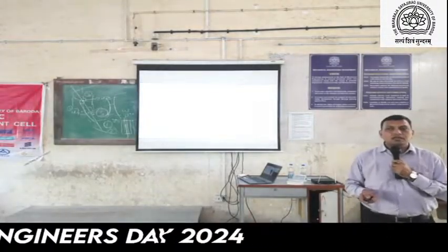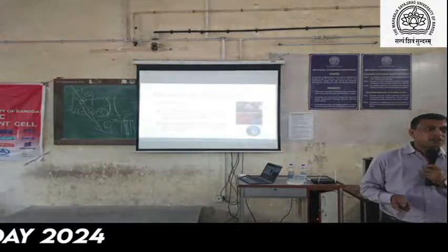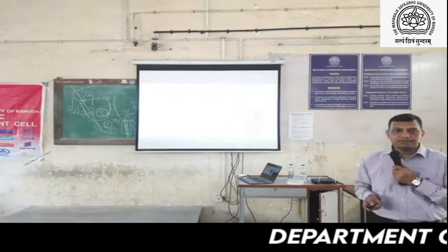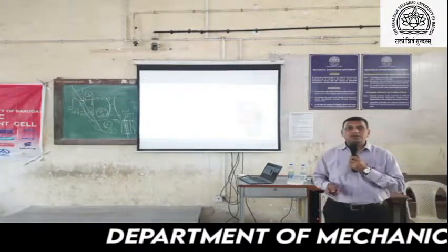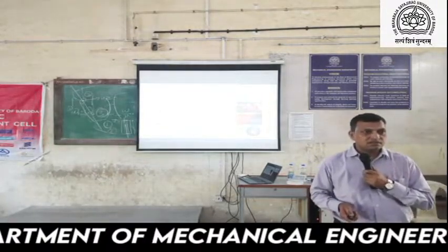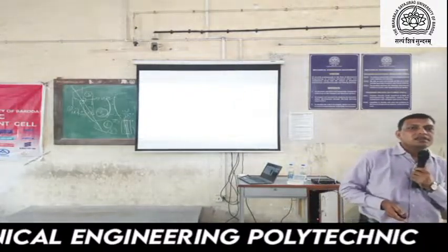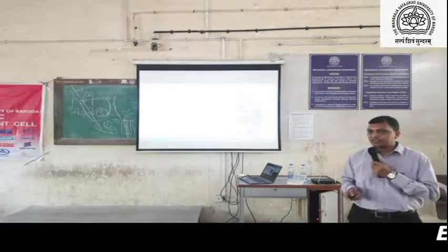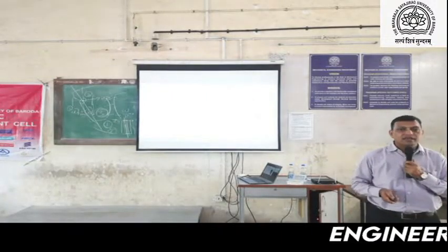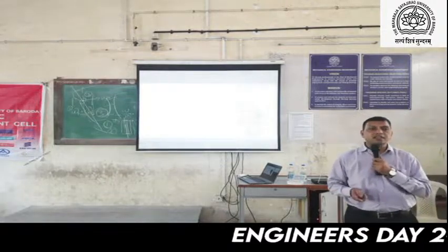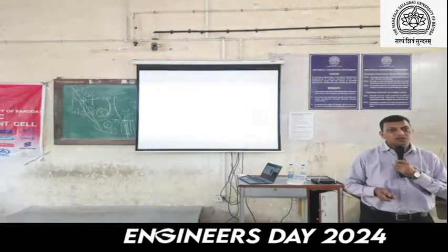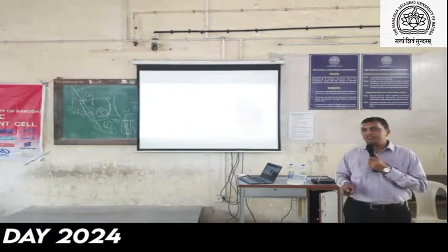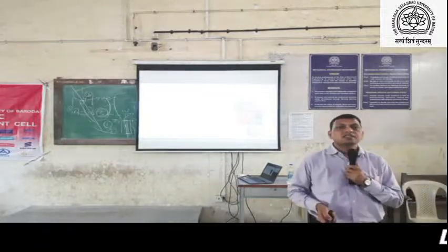After hobbing, we need to go for the heat treatment of this pinion or the wheel. So why is the treatment required? Basically, there are through hardened material and case hardened material. If the loading is not high and the speed is not very high, in that case we can use soft material for our transmission. But if we require higher load capacity, then we have to go for the case hardening of the material.